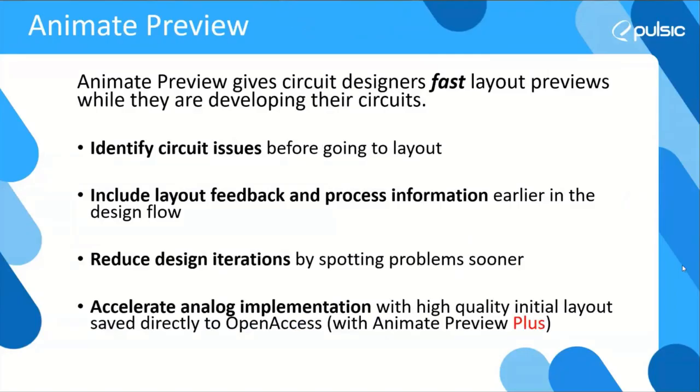And what are the advantages? Well, the advantages are it gives you very fast layout previews while you're identifying your circuit. You can identify those circuit issues before going to layout. So have you got any mismatched devices? Have you got bad parameterizations? Did you just not realize how large this was going to be and how it's going to fit together? All those sorts of things. And you can include that layout information and process earlier in your design flow.